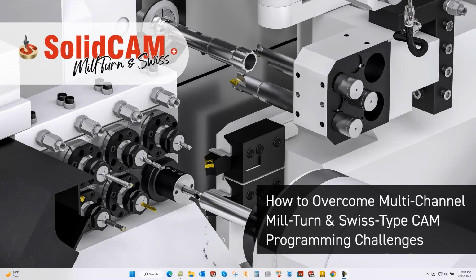You're going to use the same MCOs, but in the setup, you might have a 5C collet or a 3-jaw chuck or something like that on your main and your sub. Other than those, it's pretty much programmed exactly the same.